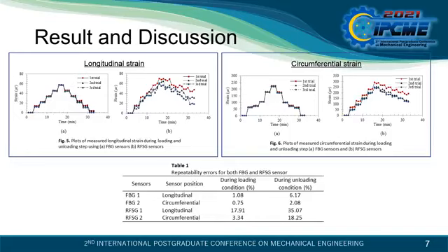So figure 5 shows the recorded data of longitudinal surface strain, comparing both sensors, the FBG and RFSG sensor. The longitudinal strain measurement data, as shown in figure 5, portray a good reasonable agreement between both sensors. The strain response is initially proportional to the pressure. Throughout the test, it can be seen that the strain response of the FBG sensor does not vary and possesses good stability and repeatability during the loading and unloading period. The stability of the output signal is a main feature to validate the robustness of this sensor for an SHM system.